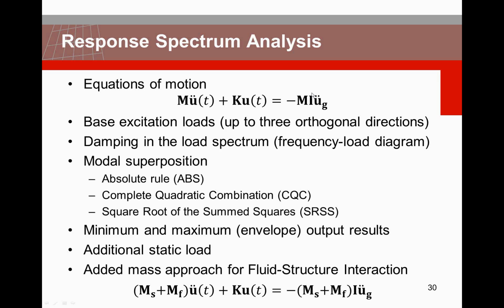This I here is a matrix which indicates which degrees of freedom correspond to the direction of your earthquake loading, your ground acceleration. That is done internally, because you give a direction for your ground motion, or directions in case you have multiple base excitation loads.